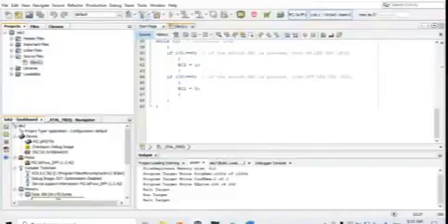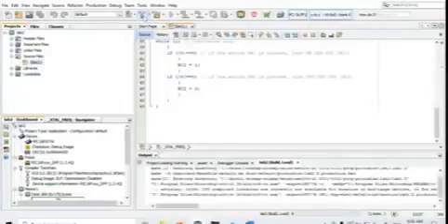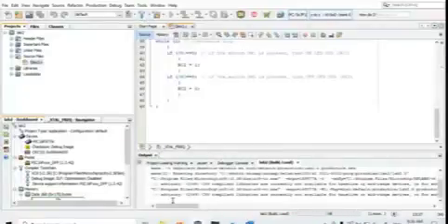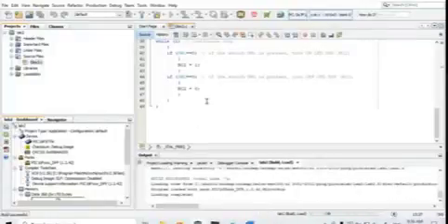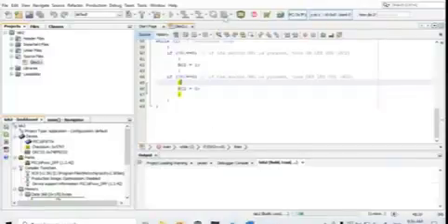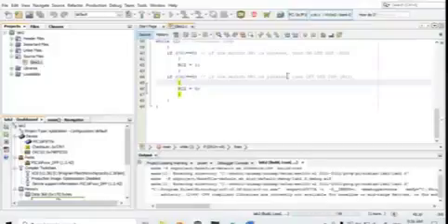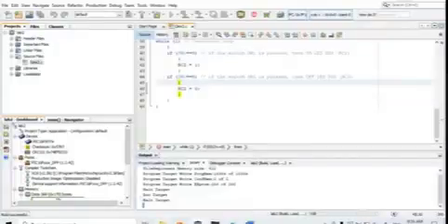And then if you are confident, you proceed to build project. Wait for build success to appear here. If not success, if error, you need to go to the code here and then do correction. Since the status is success, then you can go for debug. Okay, run target.